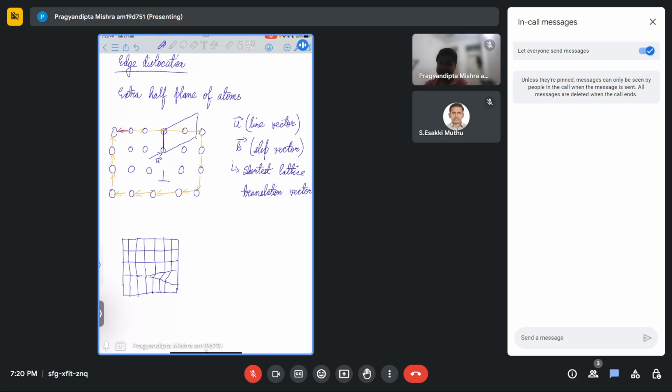Okay. So this part, this region, let me use a different pen, that we are obtaining when we are twisting the crystal. Essentially in screw, what you're doing is you're holding the crystal from two points. Imagine it happening in this way: you're holding the crystal from top and bottom and you're twisting it like this. If you have played with a Rubik's Cube, you can imagine a screw dislocation very easily.